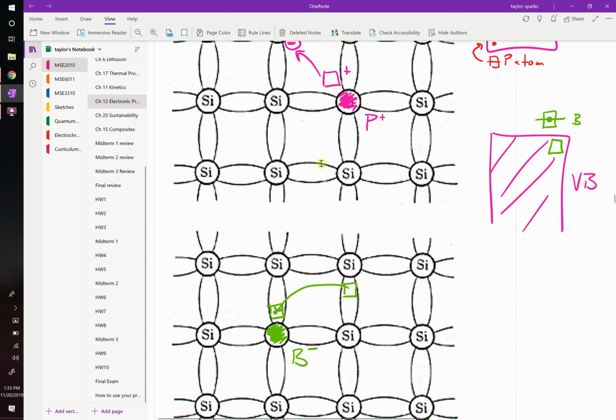The more and more boron ions I put in this lattice, if you have a hole that's traveling through this thing, remember the hole is positively charged, it sees its old friend the boron, which is now negatively charged. It might temporarily recombine with that, or at least be distracted by it. So the more and more of these that you have, even though they increase your carrier concentration, they reduce your mobility.